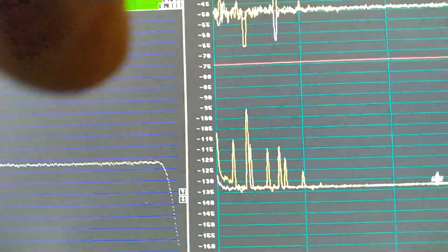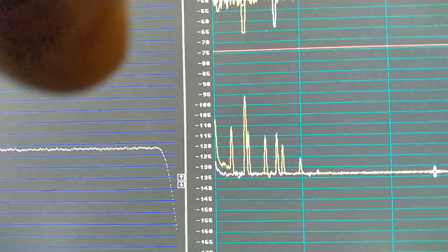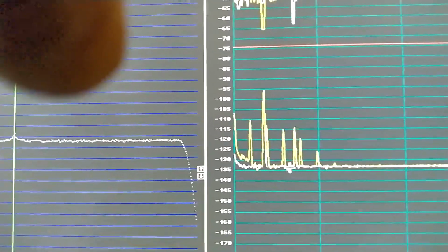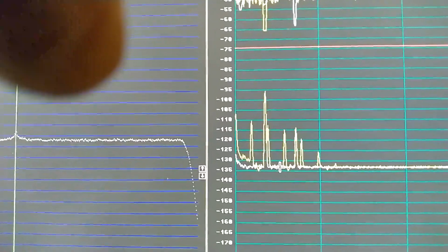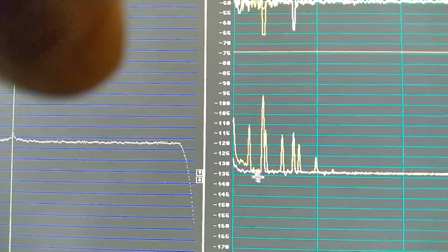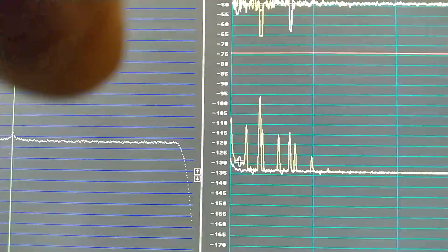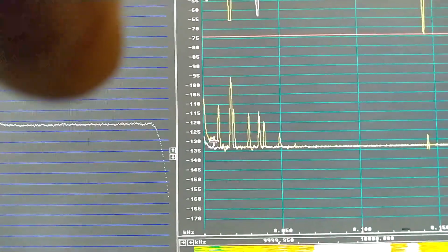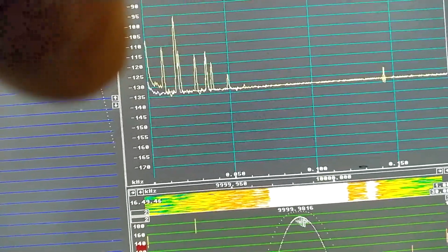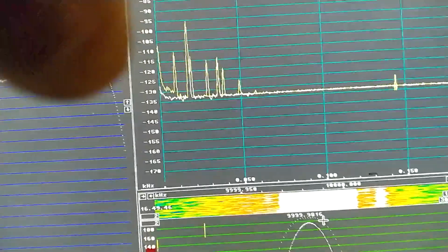And here you can see amplitude noise and phase noise are the same. Although at 30 Hz or so the phase noise starts to be noisy. But down here at 10 Hz it's no longer okay. And not surprising, because this baseband filter is about 10 Hz wide.